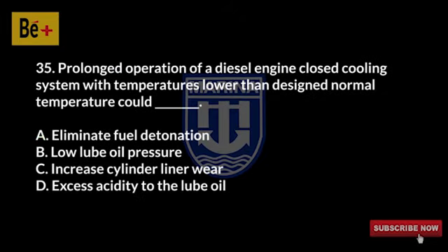Prolonged operation of a diesel engine closed cooling system with temperatures lower than designed normal temperature could A. Eliminate fuel detonation. B. Cause low lube oil pressure. C. Increase cylinder liner wear. D. Cause excess acidity to the lube oil. The answer is C. Increase cylinder liner wear.